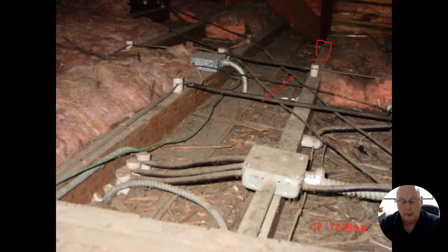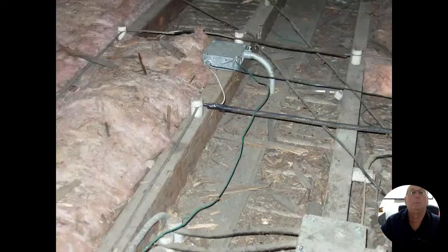All right. Now they took some of these old knob and tubes and they wanted to get some more electricity coming in here. So now we have a junction box. That's the right way to do it. All right. But if you look carefully and you see a little, I think it's a wire coming out of there, out of that junction box at the very top. It looks like we ran a ground wire and the neutral wire, and basically they just brought bare wires coming out of there. And I'm hoping we'll all realize, no, you can't do that. All right. Oh, they did.